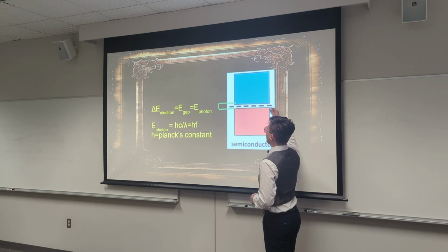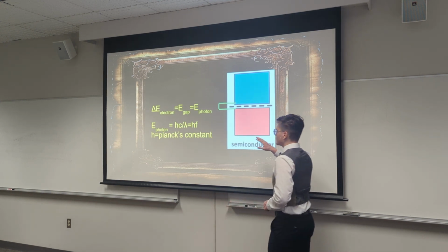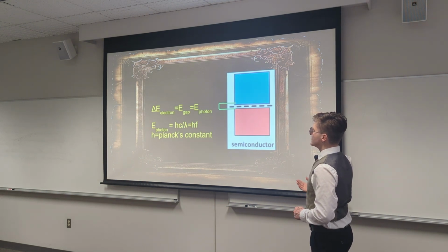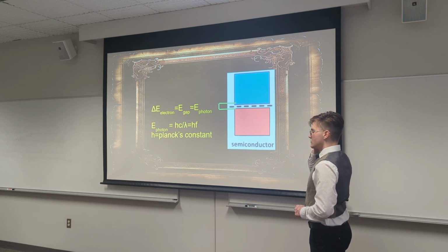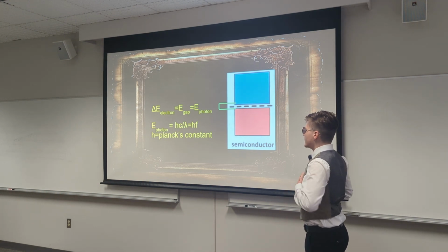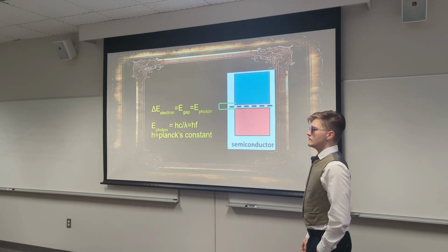So by using different materials or different concentrations of doping, we vary the size of the band gap and the output energy of that photon. Most LEDs are tuned in a way that the band gap will release photons with an energy level that we can see. I don't have any numbers in my mind, but red light and stuff like that. And some are tuned to emit light that we can't see, like in TV remotes and stuff.